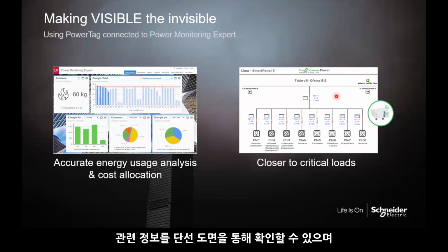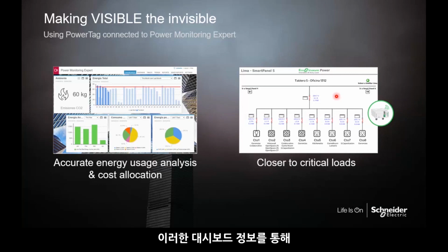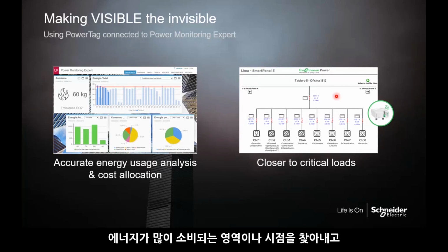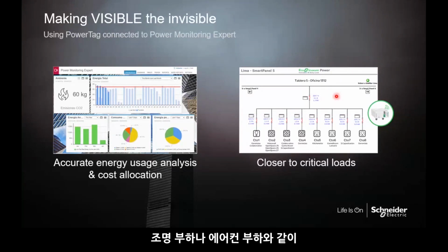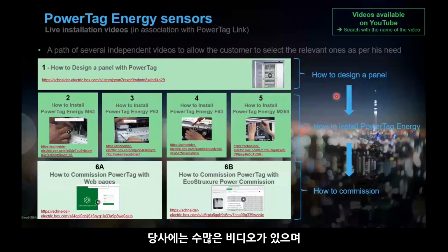We can look at things in single line drawings and at the consumption pattern, for example in a pie chart, to understand when energy is consumed in an area, how much is consumed by lighting loads and how much by aircon loads. We can monitor those using PowerTag solutions.